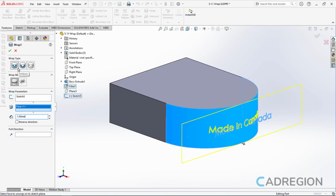The Embossed type creates a raised feature on the face. The Debossed type creates an indented feature on the face, while the Scribe type creates an imprint of the sketch contours on the face. With the Emboss option selected, I will type the number 2 in the Thickness field and I will click on the check mark to show you the final result.